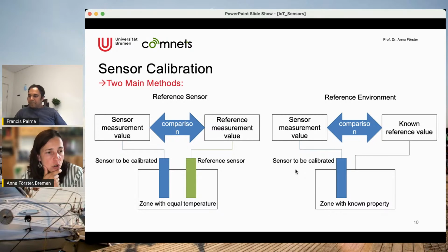The problem is that different components have different requirements. The external memory is the first to say goodbye, because it needs a very specific input voltage. The microcontroller, the ESP32, is actually the last, with the biggest resilience of all of them. And some sensors might also simply switch off or deliver wrong results, as we saw before.